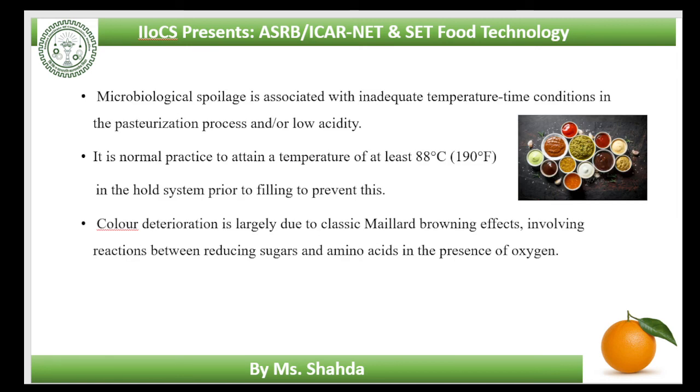Microbial spoilage is associated with inadequate temperature time conditions in the pasteurization process and or at low acidity. It is normal practice to attain a temperature of at least 88 degrees Celsius in the whole system prior to filling to prevent this.